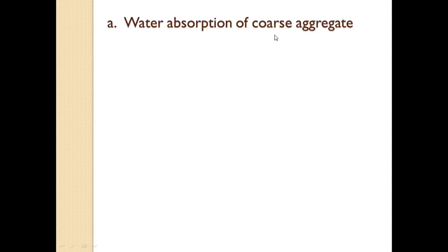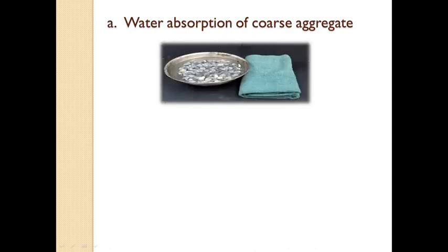We know the coarse aggregate should absorb less water. If it absorbs more water from the concrete, then the concrete becomes harsh. It will also reduce the workability of concrete.